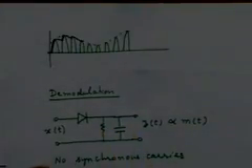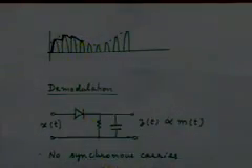As you can see, this charging and discharging phenomenon under certain conditions would produce an output which follows the envelope, right? Approximately, there will be some ripple, which you can always remove by a suitable low pass filter.